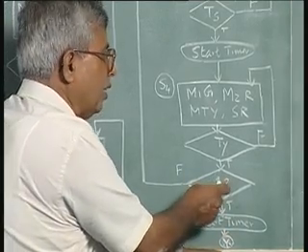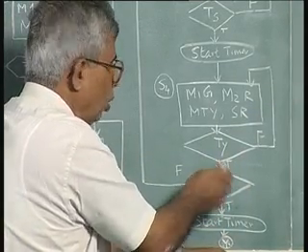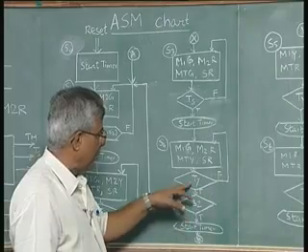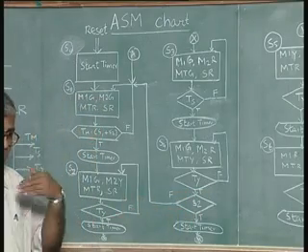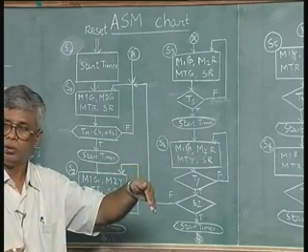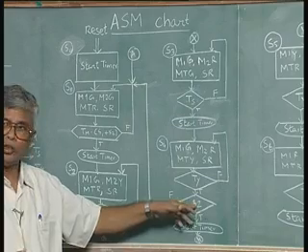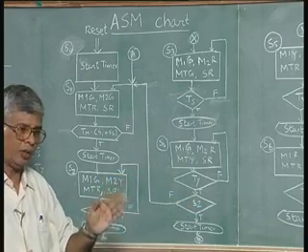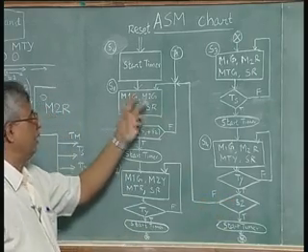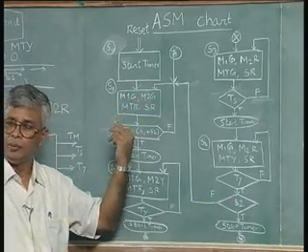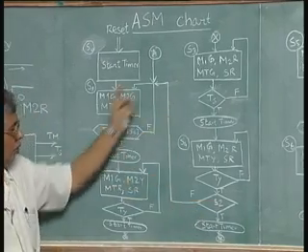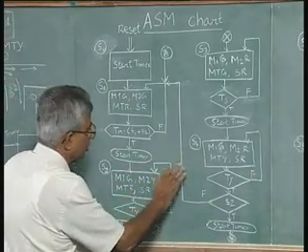Here is where I introduce the concept of S2. If you do not want to check S2, you can go through the whole cycle without this S2, you can go to the next state. But if S2 is not on, I have completed the turning from the main road to side road, right turn, and if S2 is not on, that means no traffic is waiting to turn from side to the main, there is no need to go through the other states, I can go back to the original state where that is the most preferred state, because the main road traffic is the most important traffic. So, at S2 is false, we will go here, we have to start the timer here.